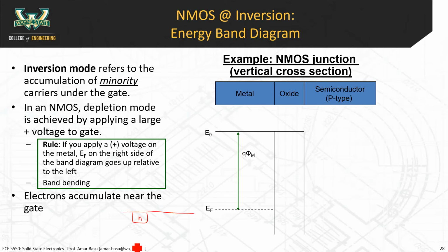You have your N-type material here, N-type material here, your gate material here. We apply a positive VGS. This time there's more charges on the gate, so the VGS is greater than VT. That's the key thing here. So that creates a strong electric field. This pushes away the holes.